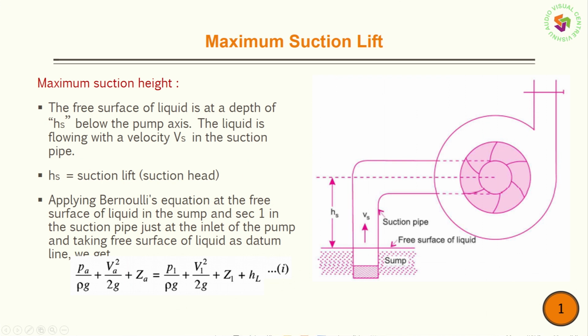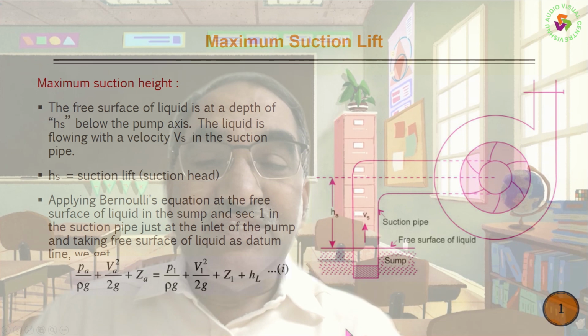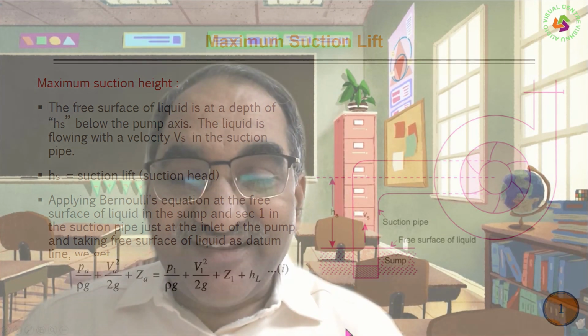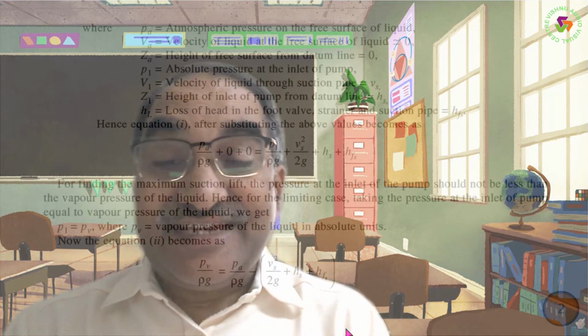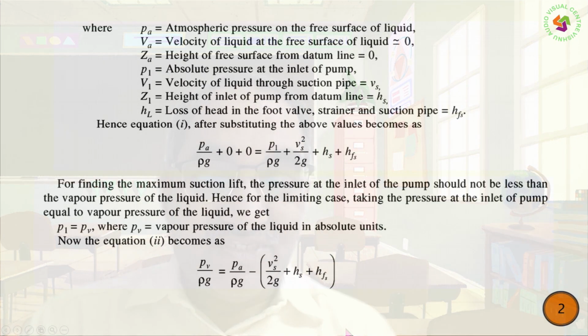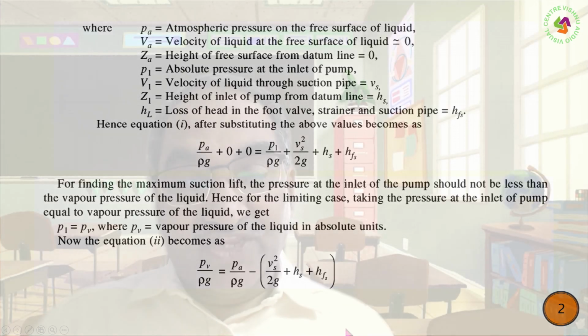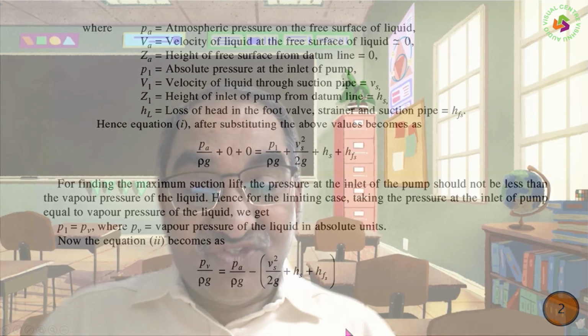The impeller gets damaged, then the inside boundary of the casing gets damaged. That is why cavitation should not occur. Compared to turbines, centrifugal pumps are more vulnerable to cavitation, so you need to study these three things.